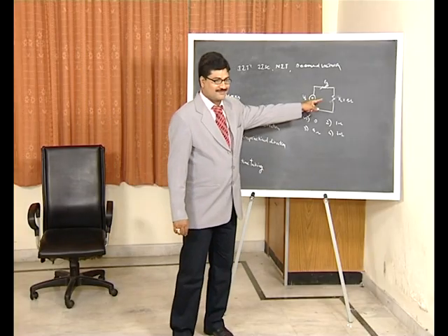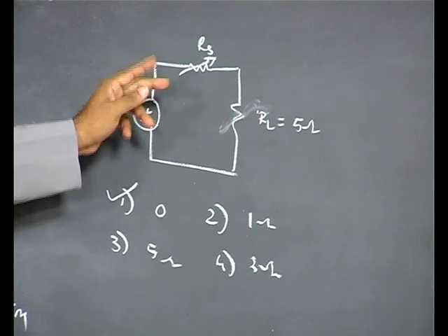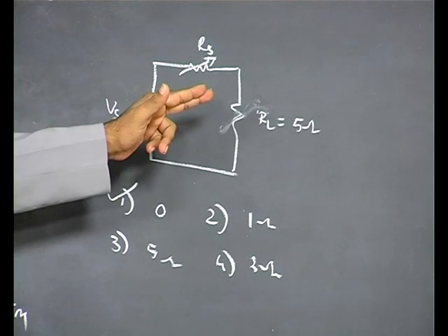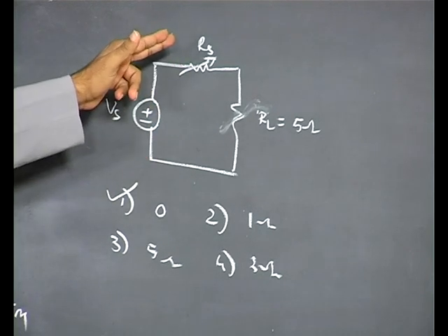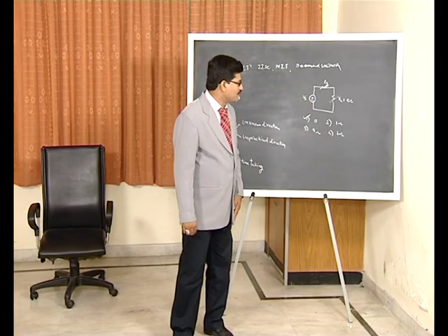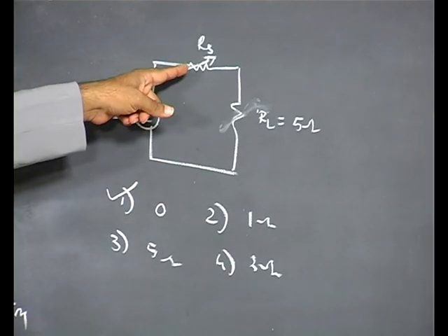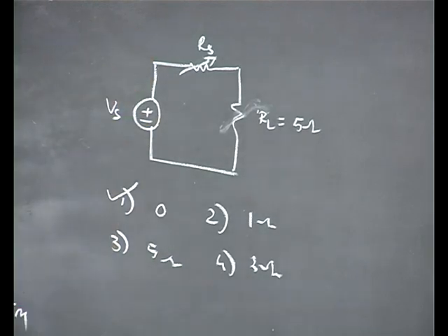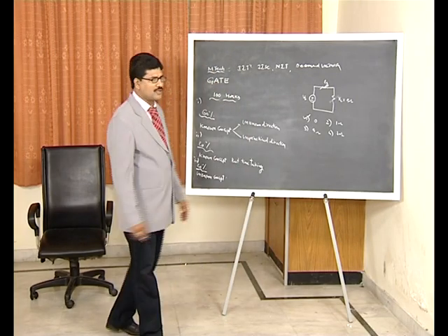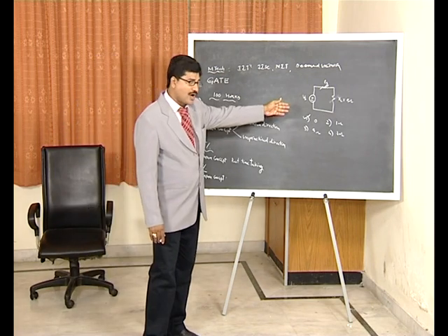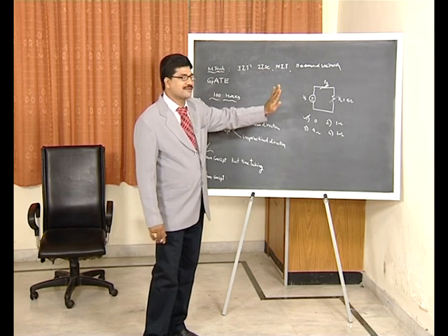But the unpracticed direction is: if the load is not varying and the source resistance is varying, then at what condition is the maximum power transferred from source to load? The source resistance RS must be minimum. Here you select the minimum resistance for the source to transfer maximum power from source to load. This type of question almost all comes in the first category. This is a known concept but an unknown or unpracticed direction.